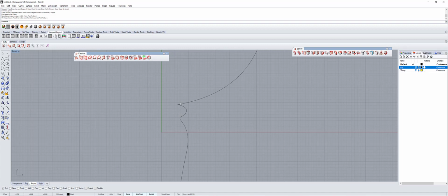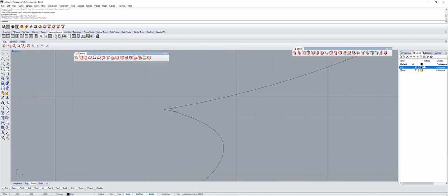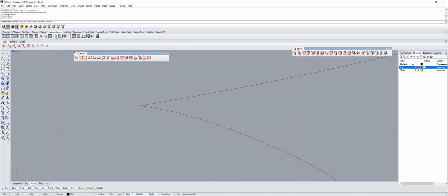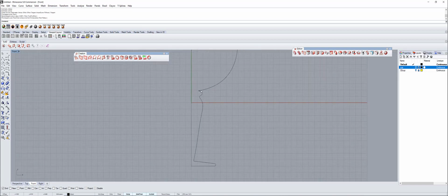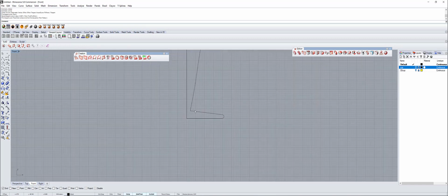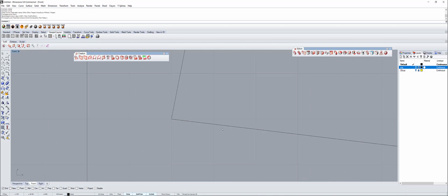So wow, this is so small. Yeah, super small. I'm going to delete this. Enter. I'm gonna tangent. I'm gonna click around here to here and click it and enter. Yeah, that's still small, but that's much better. And over here, we're gonna make the same, but this one has to be bigger. This one has to be like 1 millimeter, like the size of that square right there. So enter, click tangent, and click here, and through here. Yeah, from there to there is 1 millimeter.